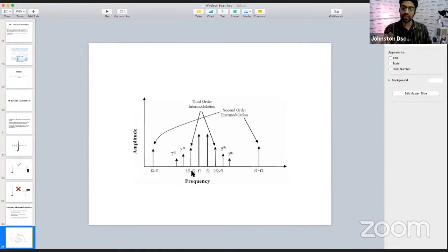Okay. Now in this case, it is telling me group number 1 has 12 frequencies free. Group number 2 also has 12 frequencies. Group number 3. So basically, there's no RF problem here. So all the banks are pretty much free. Okay. So I can choose whatever bank, open, and then it will tell me now 1.1 is 470.1 megahertz. Okay. So I can choose that frequency.